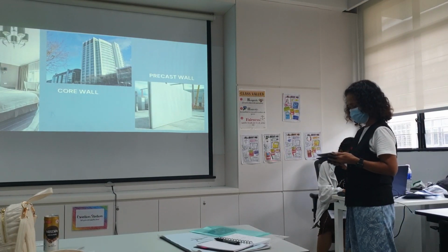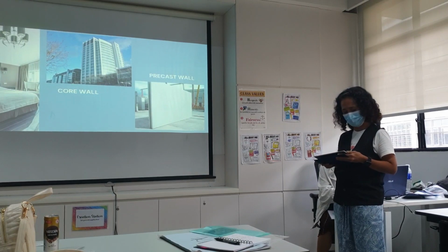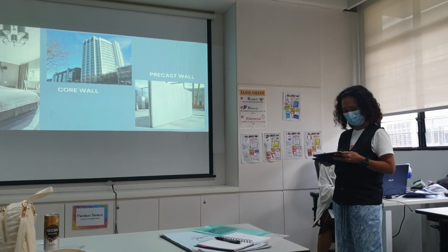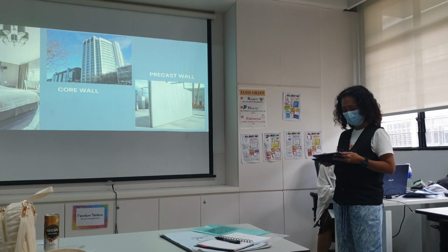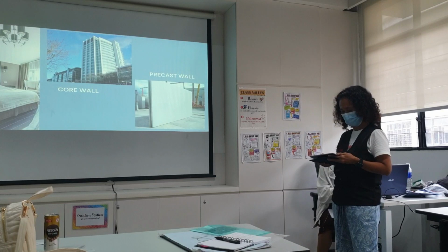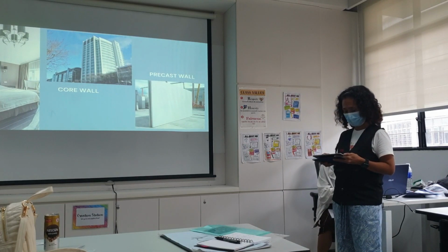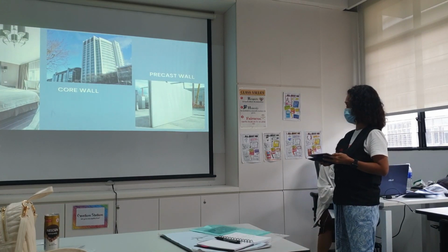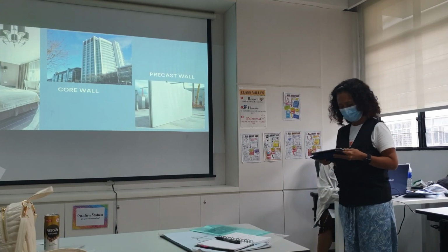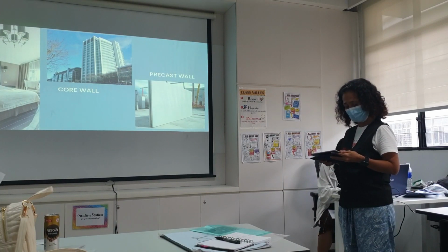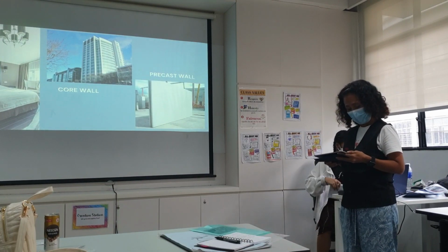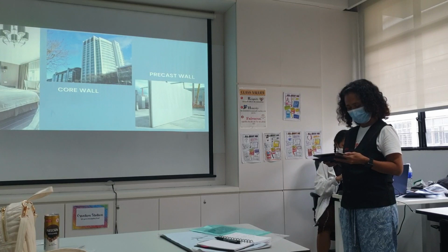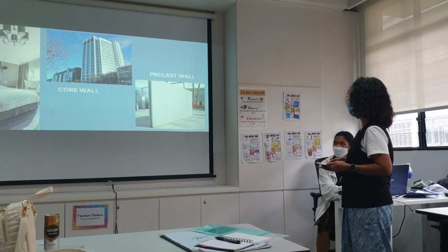Precast wall. Construction of precast concrete walls is initiated by casting concrete in a reusable wall mold or form, which is further cured in a controlled environment, transported securely to the construction site and lifted into the place of installation. The main purpose of installing the precast wall is to speed up the construction process. These walls are designed as blind divider or facade, which does not carry any load but must oppose parallel loads conferred on it.